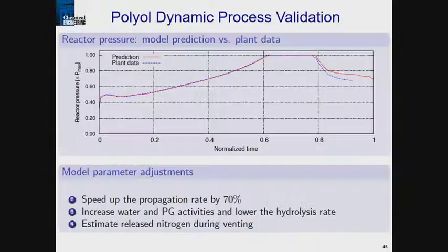This was put together by a very nice DAE model, reaction model, and this is how it validated in the plant. Now, this is only a cartoon to give you some idea of how well the data fit. And this is the pressure profile over time compared to the plant data. Over here, there's some deviation, but it doesn't matter because the reaction's pretty much finished, so they don't care what the nitrogen atmosphere was like.